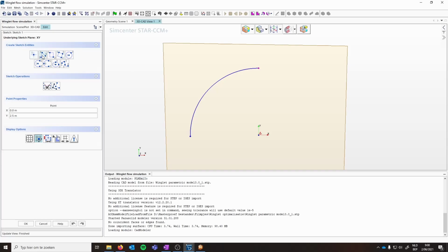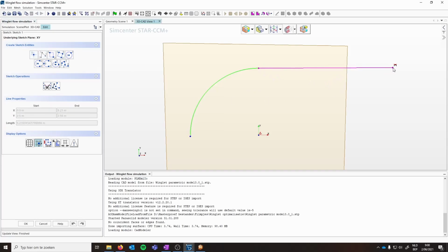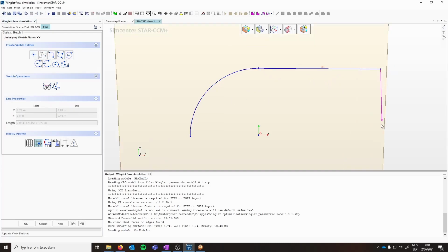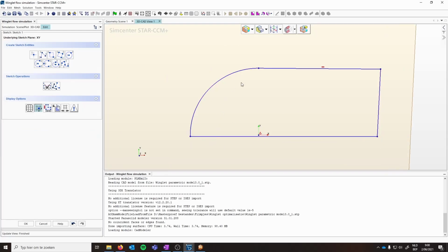So now I have to create the other part of the domain. We're only going to make half of the bullet shape so that we can revolve this around this axis. This point here, okay. In this length, I'm going to make it a bit longer to capture the full flow profile of the wing. So I'm going to put this at 3 meters.